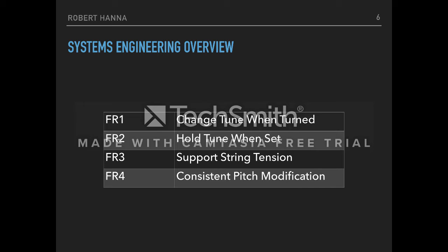First, they are able to change the tune when turned. So that's the whole point of the tuner, to modify the pitch by string tension. Number two, hold the tune when it is set. So that means when we're not turning, we don't want the pitch changing, simply put. Number three, support the string tension. So we do not want the capstan post to snap under the tension of the string.